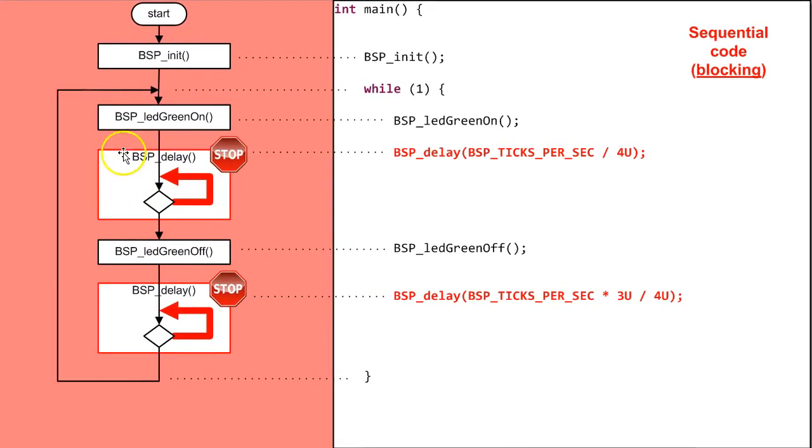When you draw a flowchart of this background code, you can see arrows going backwards against the flow of control. These are the polling loops where the code spends the most of its time, and therefore they are shown with thick lines. I will call this type of code both blocking and sequential. The code is blocking because it waits for events, such as a timeout event after expiration of a delay, in line and does not progress until the expected event arrives.